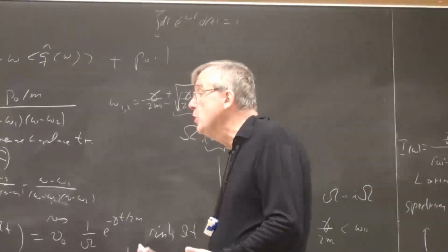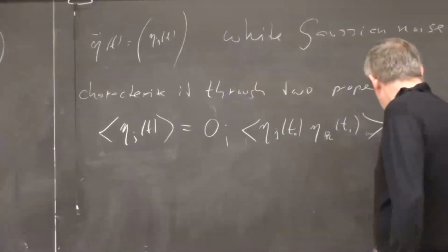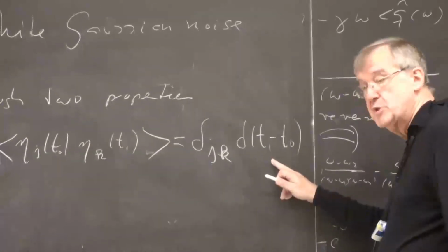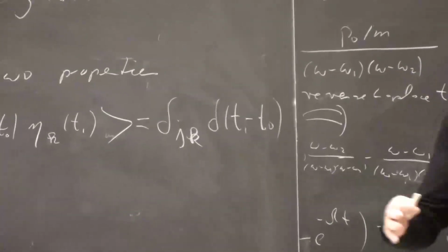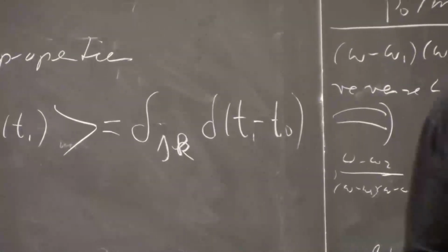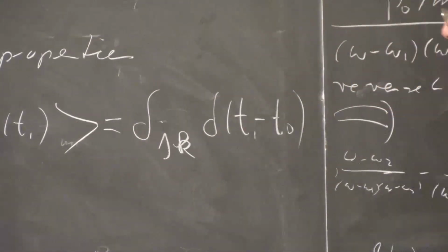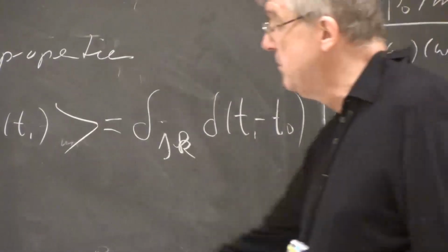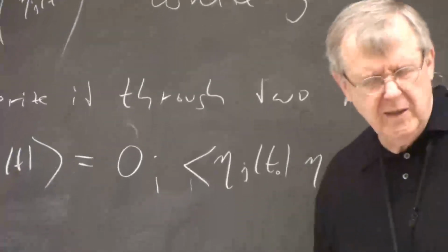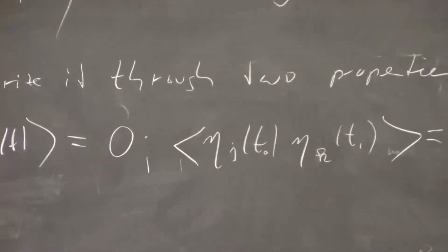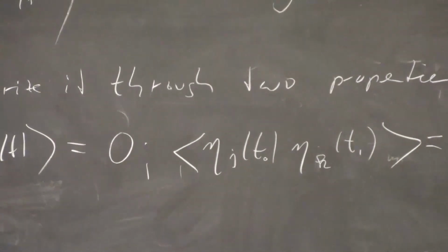Okay, and you do not need more properties when you do Gaussian white noise. White, you call it, because the Fourier transform of this one is constant. That means every frequency is equally represented, just like white light at every frequency. We call it white noise because of this delta function. It's really a very, very quick loss of memory. We call it Gaussian because it is really Gaussian. If you want to generate it in the computer, you have to generate univariate Gaussian random numbers.